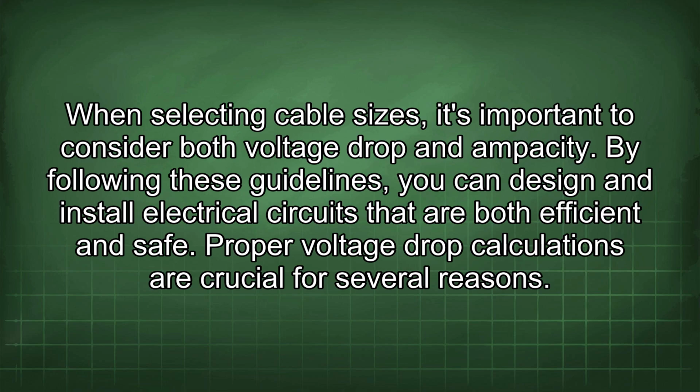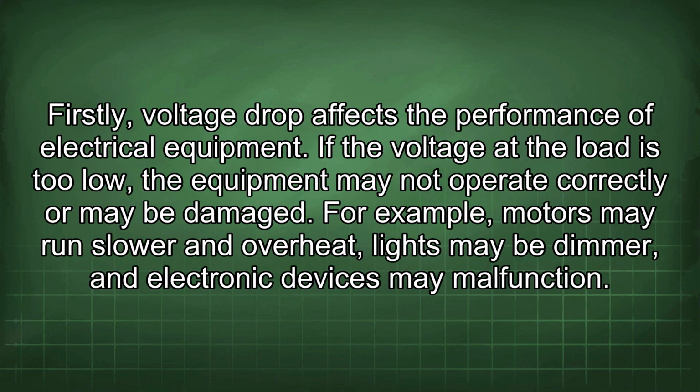Proper voltage drop calculations are crucial for several reasons. Firstly, voltage drop affects the performance of electrical equipment. If the voltage at the load is too low, the equipment may not operate correctly or may be damaged. For example, motors may run slower and overheat, lights may be dimmer, and electronic devices may malfunction.